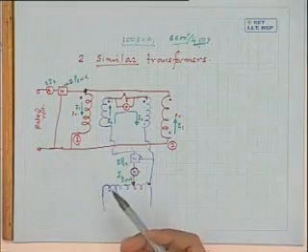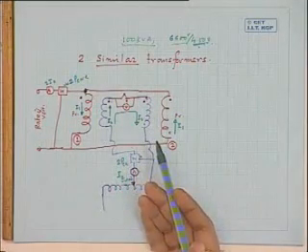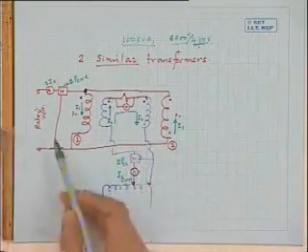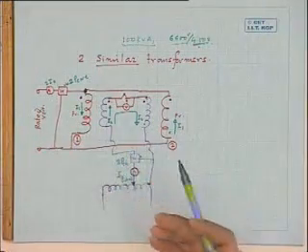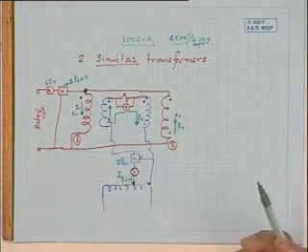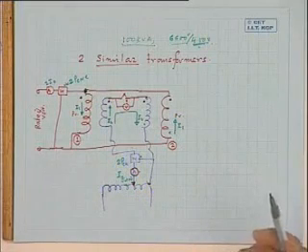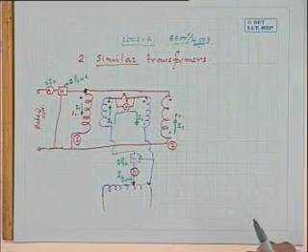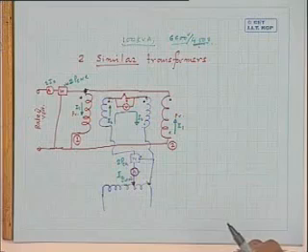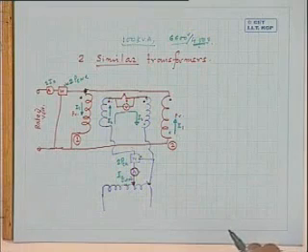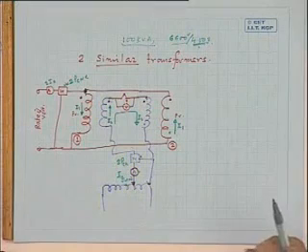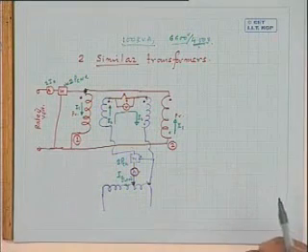The advantage here is how much power is drawn. Of course, two sources are necessary, but how much power totally is drawn to carry out this test? Only the core losses of the two transformers and the copper losses of the two transformers. And you know the efficiency of the transformers is quite high. Those losses will be very small. In other words, what I want to say is that the transformers will only draw the losses, but the observer will be feeling that the transformer is fully loaded.